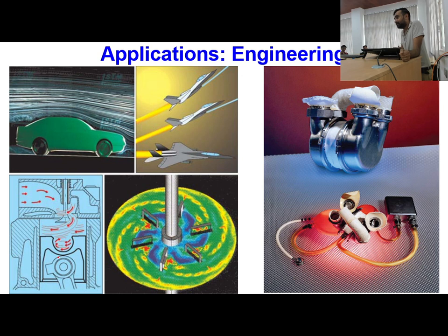The fluid mechanics of this, how it is mixing and what path it is taking, decides the combustion characteristics within the engine. If you do not have proper mixing of air and fuel, you will not get better combustion efficiency. A significant portion of the fuel can come out unburnt in the form of exhaust gases. So you see fluid mechanics is involved.